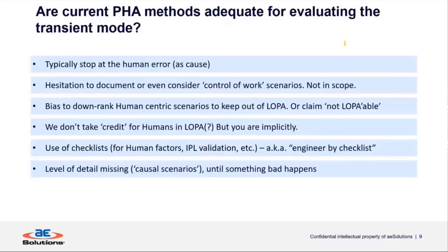There could be a bias to downrank human-centric scenarios to keep them out of LOPA or claim they're not LOPA, which they aren't. LOPA is not the proper place to do a scenario that has a heavy human factors component, human administrative controls, human error. It's really not LOPable.